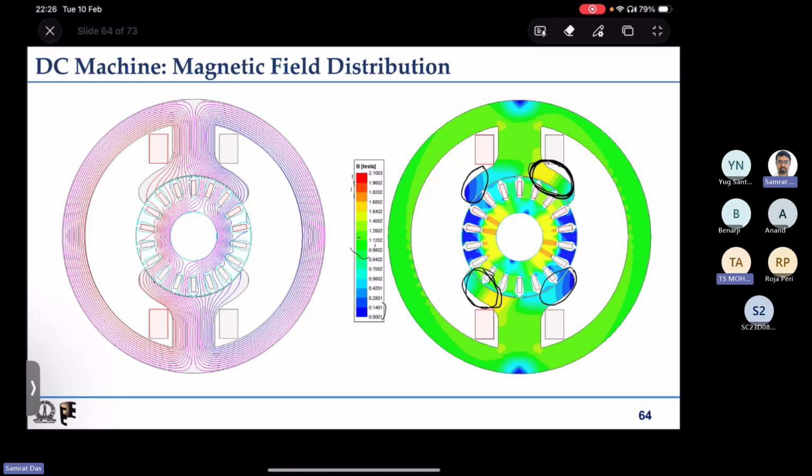But we already discussed the torque is proportional to the magnitude of the field strength multiplied by the cos of the angle between them. Yes, that is in a gross sense, but what happens at a local point to point at different points on the rotor? There will be a local force distribution that will add up to get the torque.